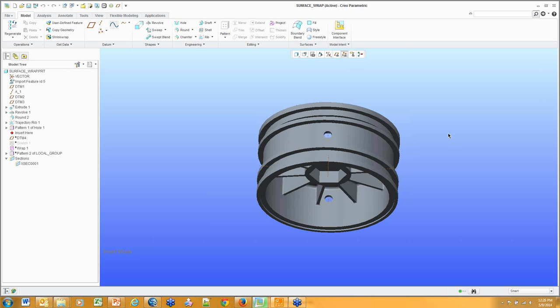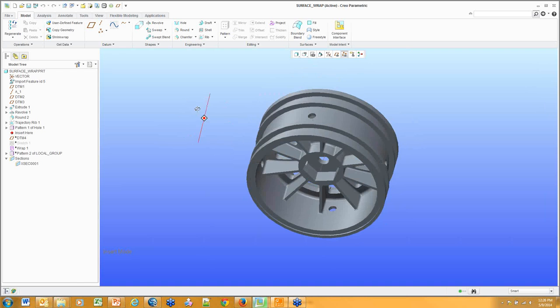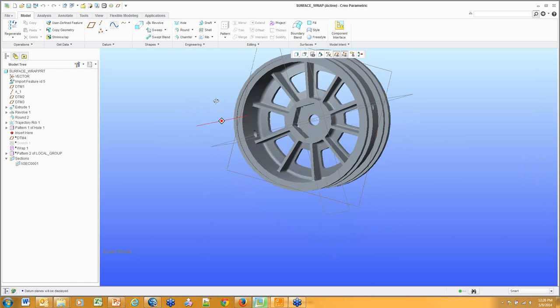It's not too tough at all with a surface. Here I do not have a surface. Here I have solid geometry. In fact, this is imported solid geometry. So what are we going to do? Are we going to copy and paste every single surface to create the surface region that we want to work with, or are we going to just work with what we have? So what I'm going to do is start off, I'm going to try datum planes on here.